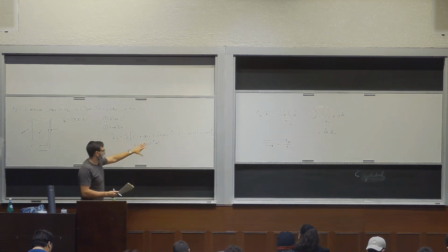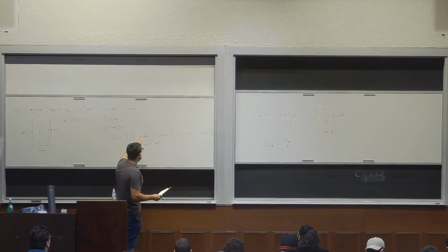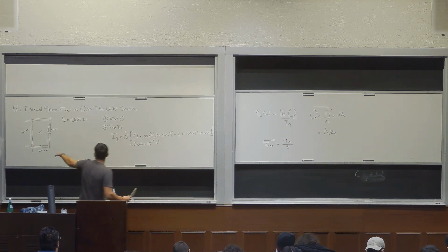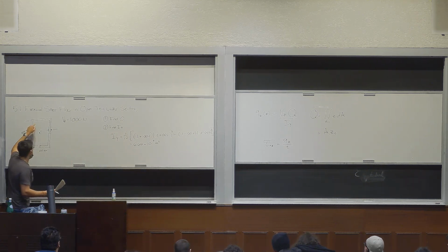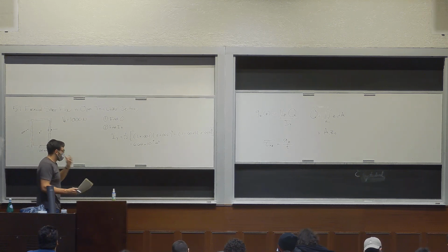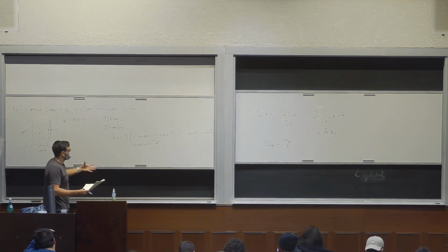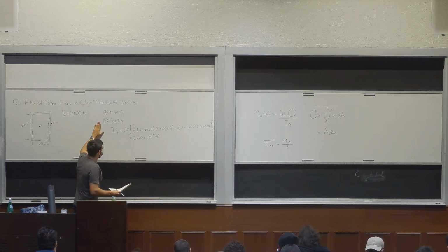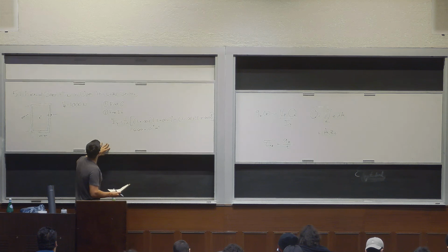The explanation for why the equation looks like this is they're basically taking the moment of inertia of the big rectangle and then subtracting the moment of inertia of this inner rectangle. So that's all that's happening there. Remember, moments of inertia, you can add them, subtract them. It's easy, right? Simple as that. You guys can do examples on that if you need more information.